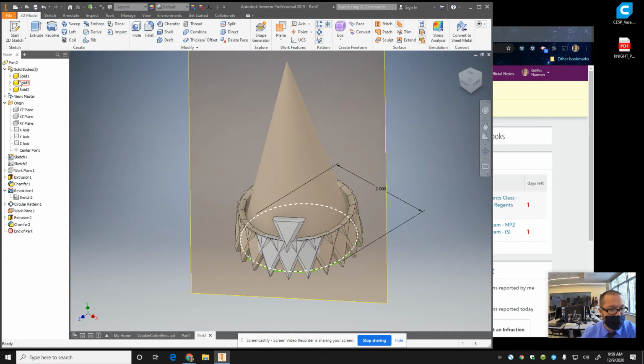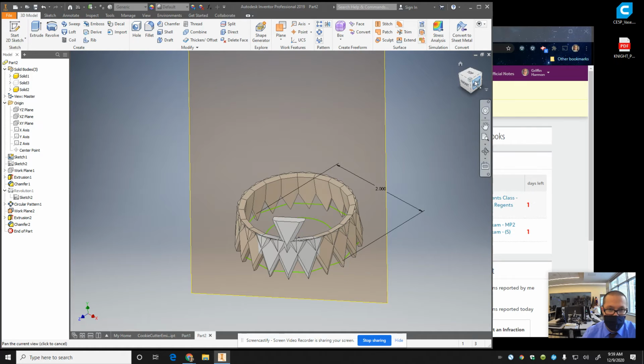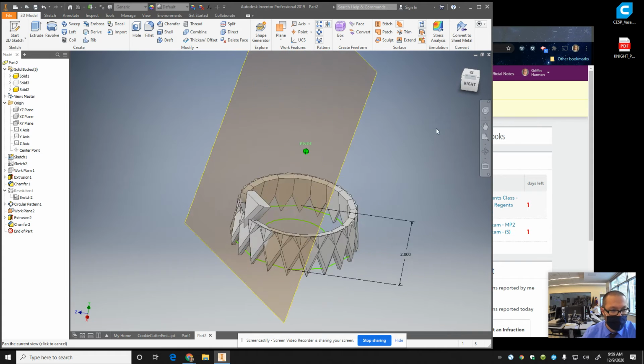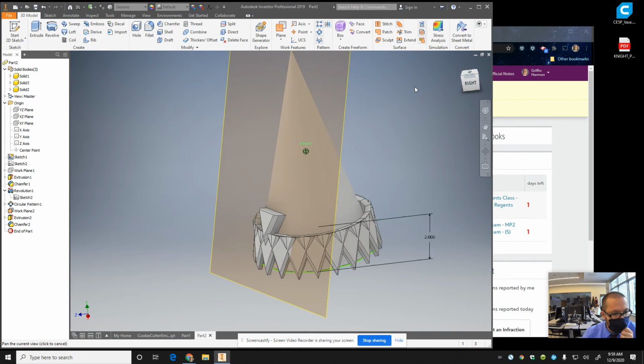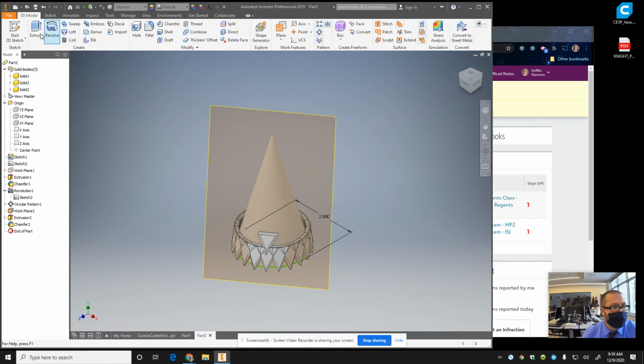All right, so we have 3 solids. And what you can do is when I go to export this, that cone that I made, I can actually turn off its visibility and it won't export as part of the STL, which is really a cool thing. Anyhow. All right. So it's in there, and let me try revolving it now. I bet it'll work. Or circular pattern it, sorry.